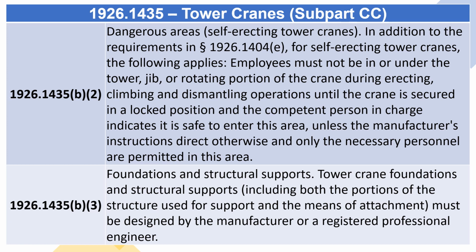1926.1435(b)(3), Foundations and Structural Supports. Tower crane foundations and structural supports, including both the portions of the structure used for support and the means of attachment, must be designed by the manufacturer or a registered professional engineer.